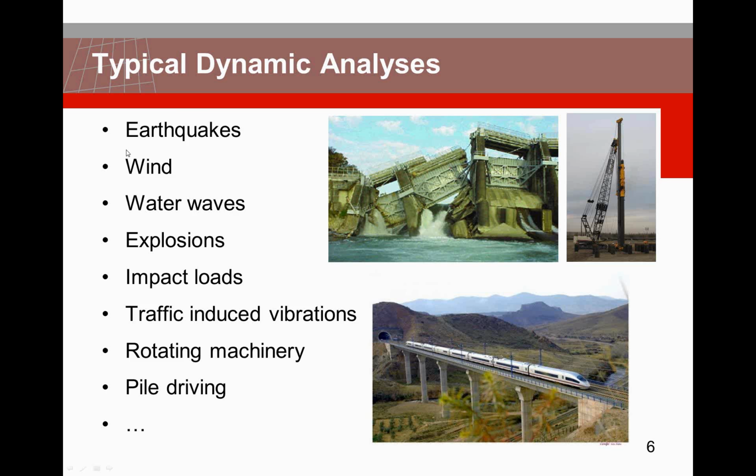Then you can think about wind loads, for instance, if you have to design a building close to the sea where you have quite severe wind forces, and wind waves or water waves, if you are working offshore, will also act as a driving force on your structure. Another type is explosions. Here it is a very short type of loading, but it can result in, for instance, shock waves that hit your buildings and get them into vibration.